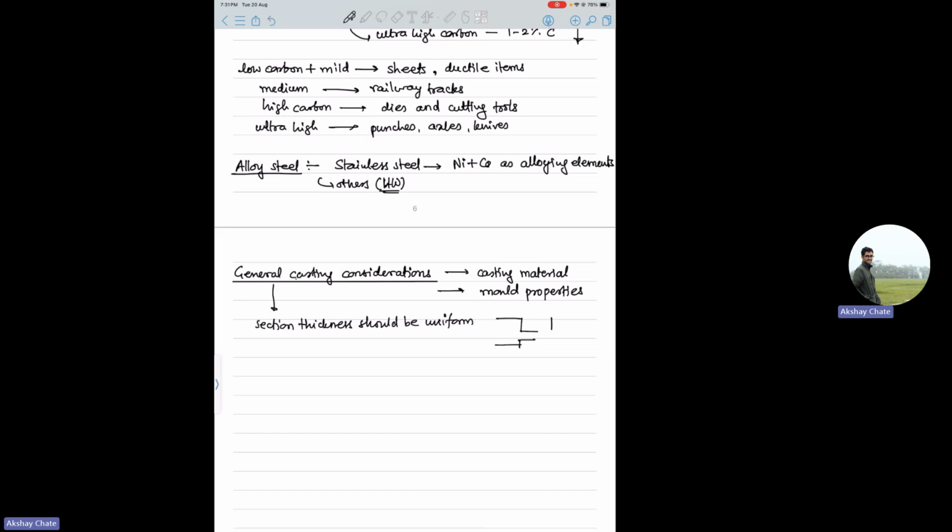You have to make the mold like this. Okay, like this. And then you do the machining operation after the mold is produced, and then make this. So this is better than this, because if you have thickness changes, etc., there are stress concentrations at the joints, and all those things are there.